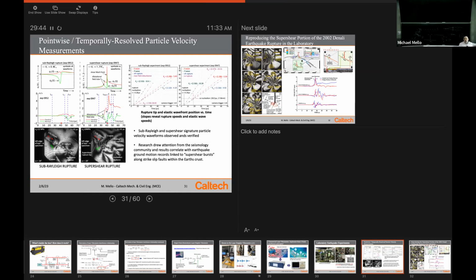The DIC ones, they look impressive, but they're all post-processed in the computer. To me, what was so elegant and beautiful about this is that this is the material speaking to us, because it is a stress birefringent polymer, okay? And it does something to laser light, okay? We don't speckle the surface and then process it. You could see this image on a sheet of paper, literally.